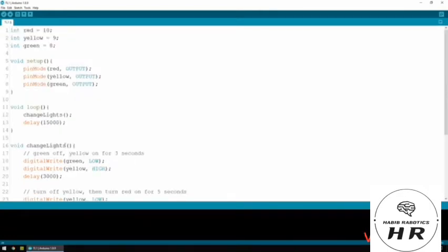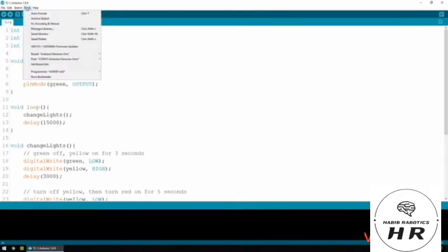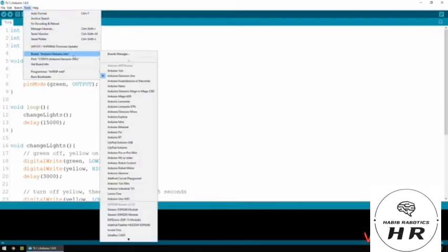Now, if you haven't already, plug your Arduino into your computer via the USB port. You're going to need to make sure that it's set up correctly with the Arduino IDE, and the way you do this is by heading up to the Tools menu here, and looking down under where it says Board. Now I am using an Arduino Uno clone today, so that is what I have selected. However, no matter what kind of Arduino that you have, you will find it in this list.